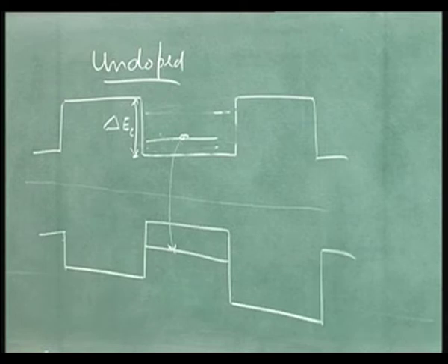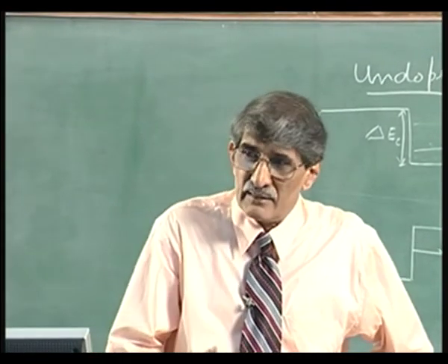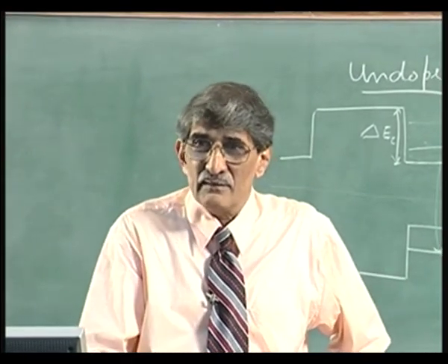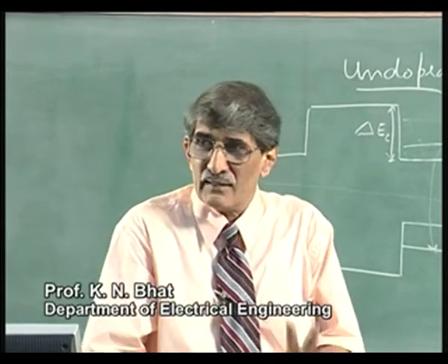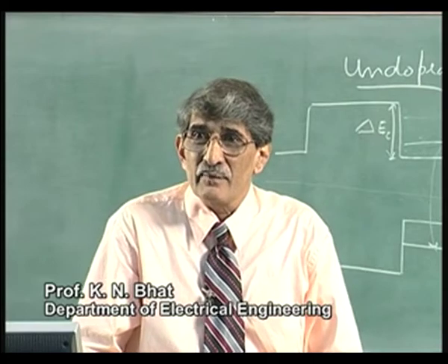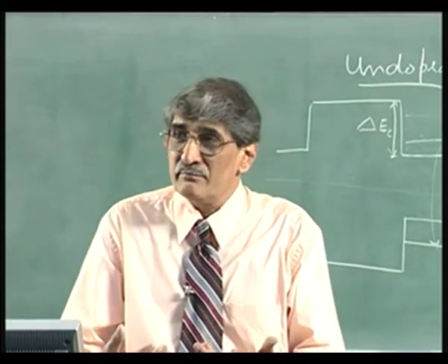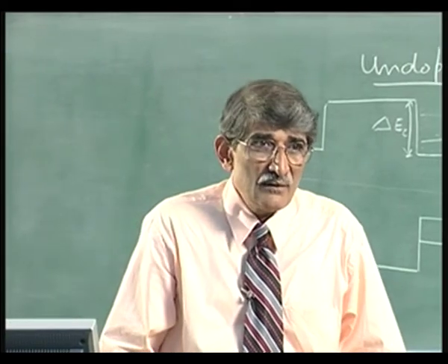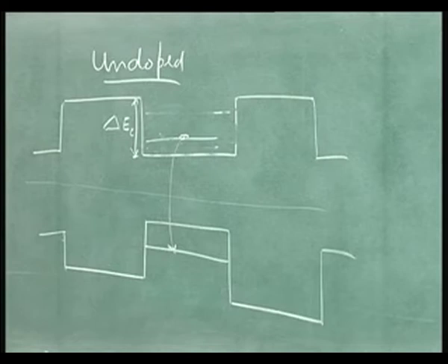So, you can see the compound semiconductors give you the facility not merely to adjust your band gap by changing the material composition, gallium arsenide, GaAs to AlGaAs. By changing x, you can change the band gap. Plus multiple layers you put alternately, it gives another dimension altogether. So, for optoelectronics applications, that is another thing. But here what we are talking of is the transistor. You do not need multiple layers.